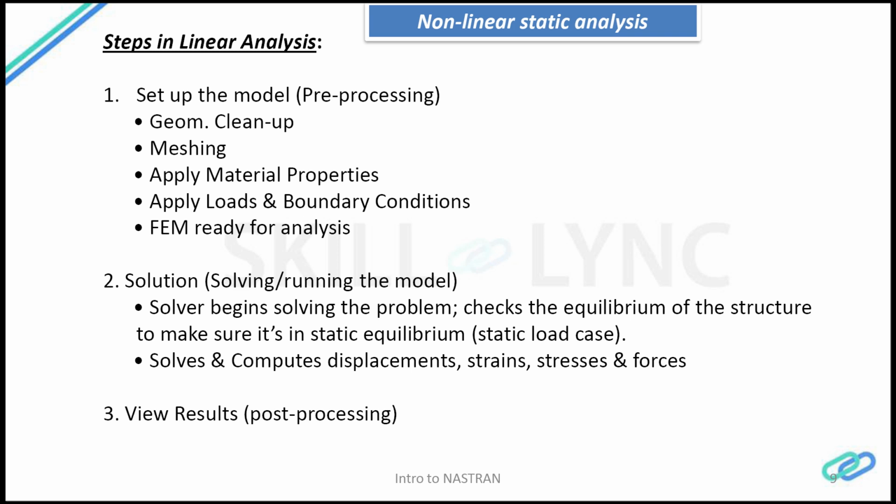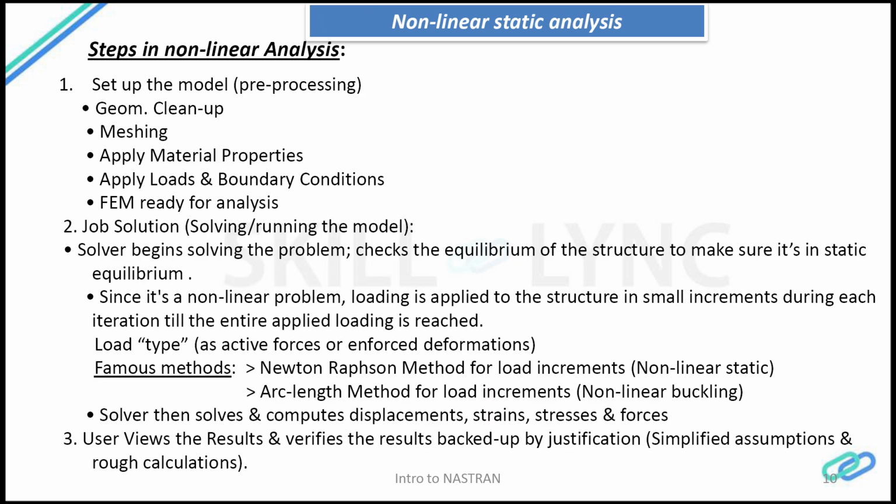So now we'll move to the nonlinear static analysis, where the first step is exactly similar to what we have done before. It's just setting up the model. Again, you have to have the geometry cleaned up, and then meshing, applying the material properties, loads and boundary conditions, and having the model ready for the analysis.